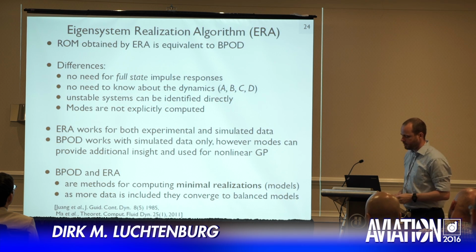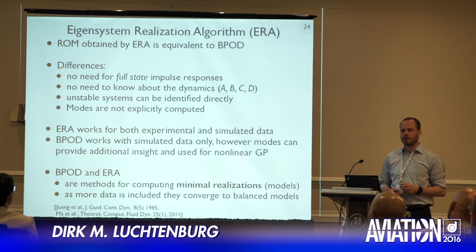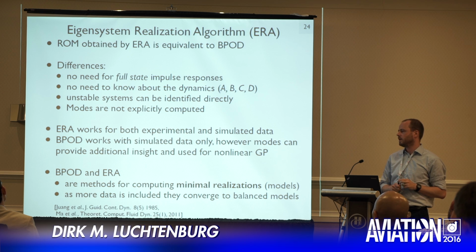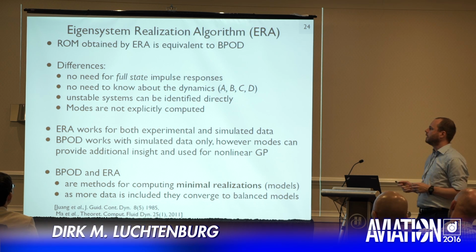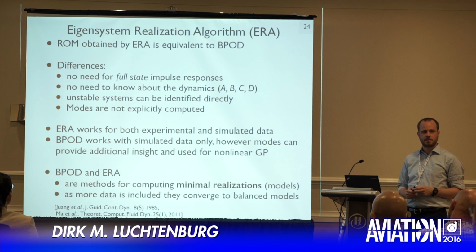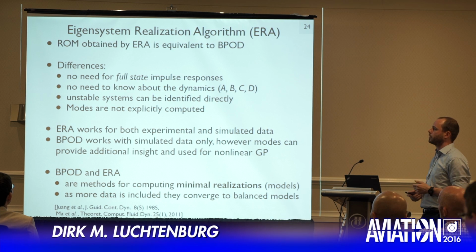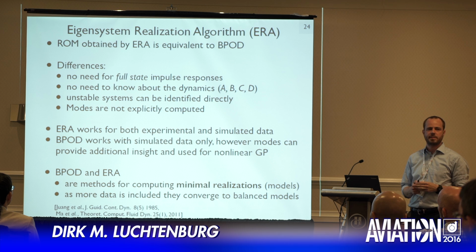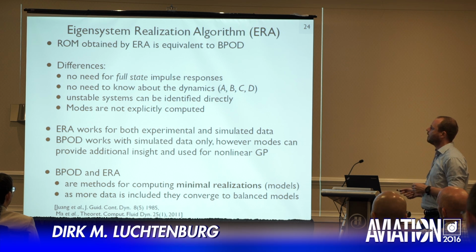Finally, I'd like to talk about a model procedure. These two model procedures, with the POD and the BPOD, were all based on Galerkin projection. Now there's an equivalent method to BPOD, which does not require adjoint simulations, and you can just work with the impulse response seen with a sensor. This means you can actually apply this method to an experiment.